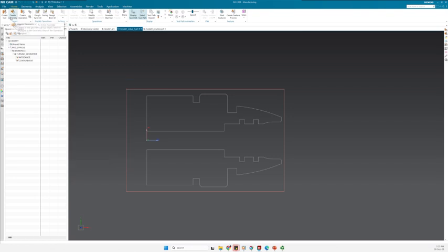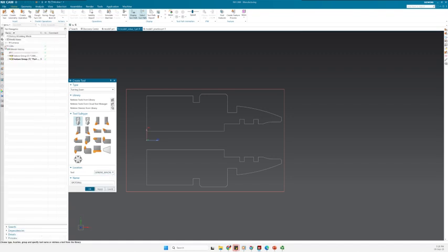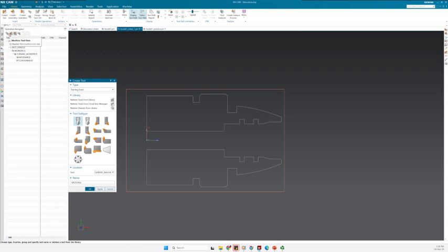If not, you can also create the tool itself, for example. So we can already create a spot drill before we go to the next video. So we are defining a spot drill for essential drilling. And then we can define the spot drill. Just to make sure we are defining it correctly, I can always check here with the tool itself. So I can see that tool station number 2 is empty, as it is also available here. I call it a spot drill.